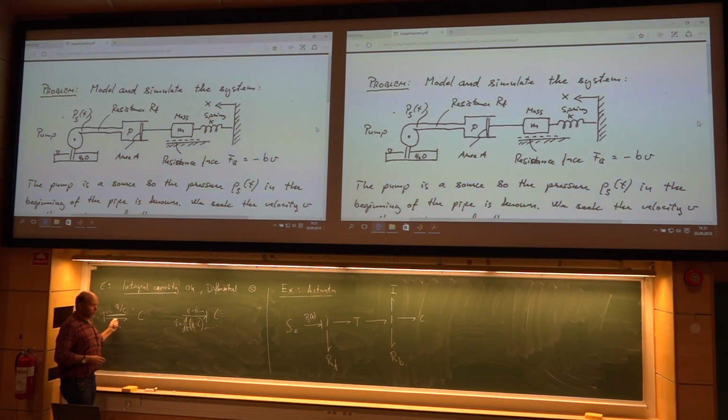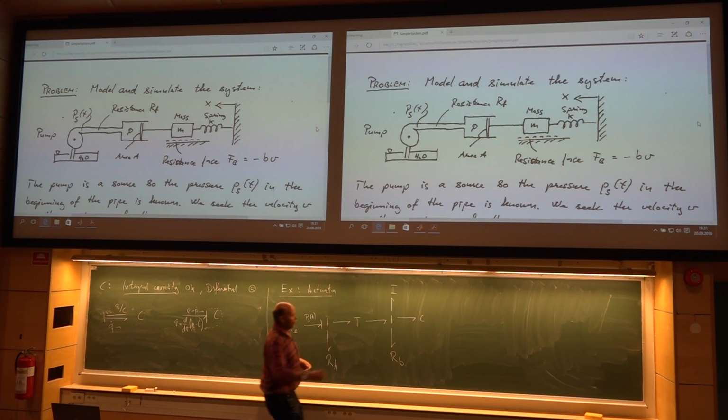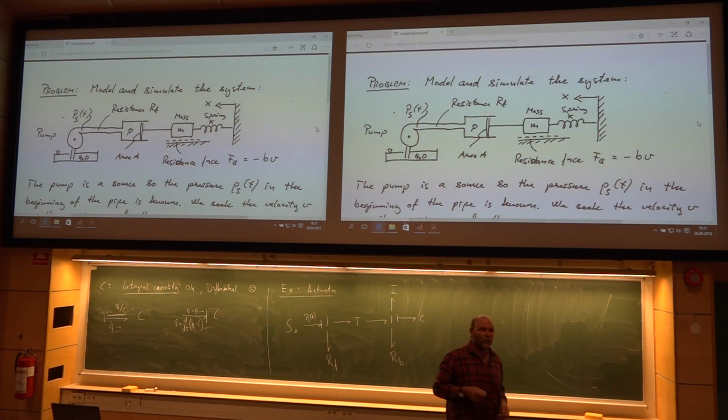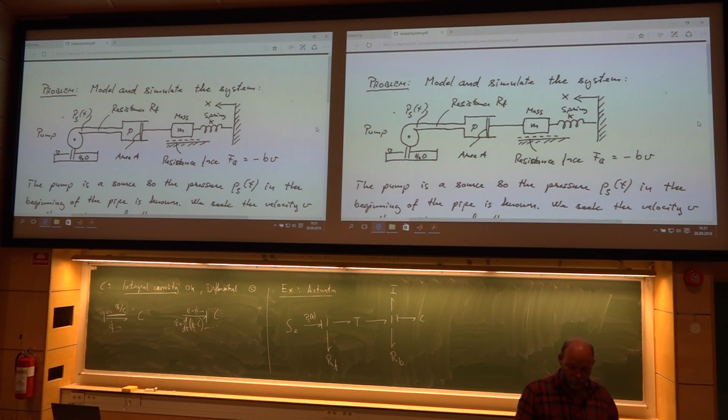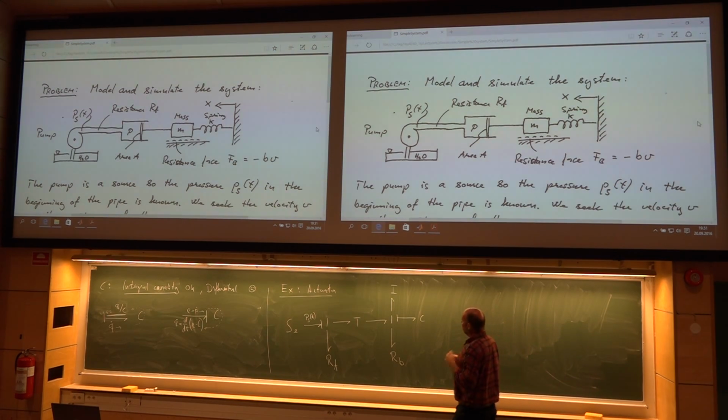I choose this one. I choose a stroke here. Then the C element has gotten the correct causal form. It's the integral form. Yes, I like it. This is good. Does it help me now with the rest of the strokes? Well, actually, no. I have a one junction here. He should have all but one strokes towards him. So this doesn't dictate anything.